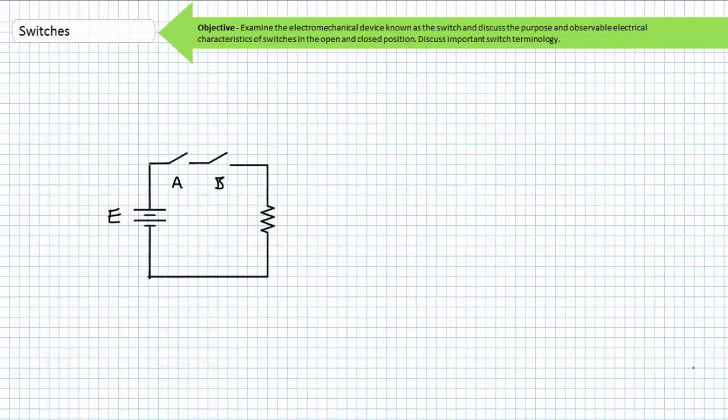As complicated as I may have made this subject seem, switches in series are routinely employed to perform one of the most basic logical functions, the logical AND. Consider two switches in series with one another, switch A and switch B, and an electrical load, perhaps a solenoid controlling a hydraulic press.